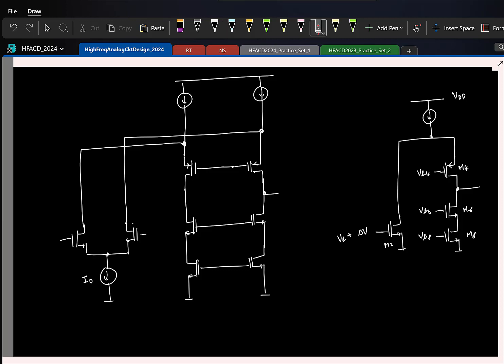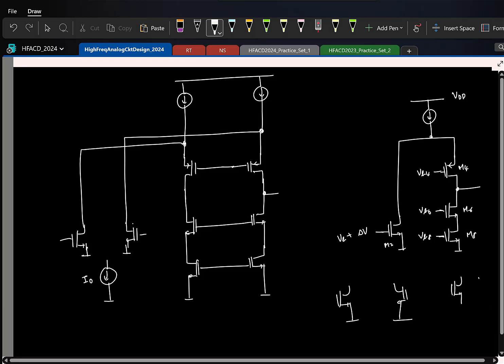Okay, so why are we having this current source actually? I mean, that was doing something else also. I mean, I could also do this. You could have a differential amplifier also like this, right? Why don't we do this? And why do we do this? Remember that your circuit has to respond only to differential signals and not common mode. If you recollect, in the common mode response, we saw this tail current source is what was providing that common mode rejection. If you don't have it, it is going to respond.